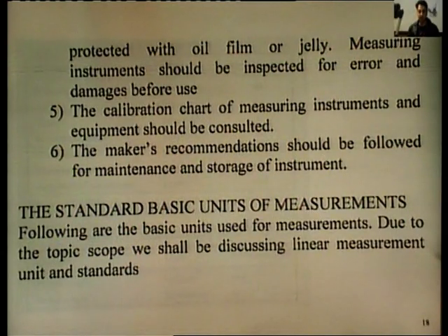And the last point is, for taking right measurements, the maker's recommendation should be followed for maintenance and storage of the instrument. So the instrument should always be kept safe from dust, heat, and it should not catch rust. So some kind of oil film or jelly film should be provided on the instruments.